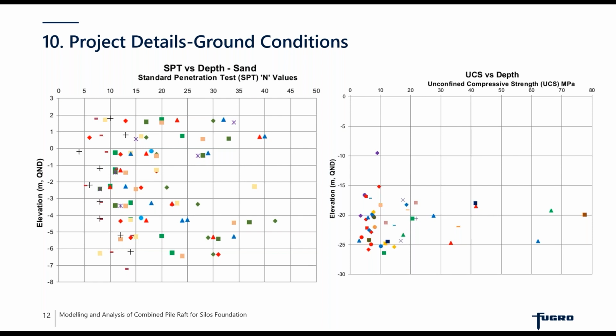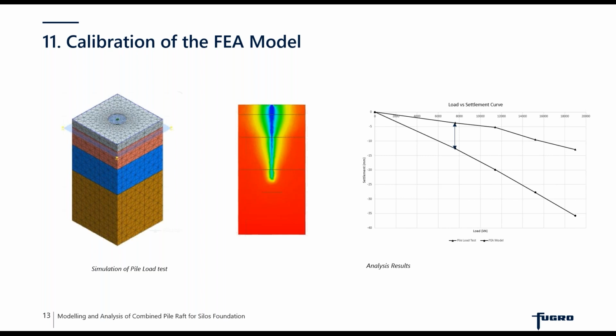Initially, the piles were designed and the pile lengths were calculated considering the ultimate criteria, and based on that the pile length was calculated for the given working load conditions. For the working load, which was around 7,500 to 7,600 kilonewtons, a pile load test was also performed to 2 to 3 times the load to check the capacity requirement of the pile.